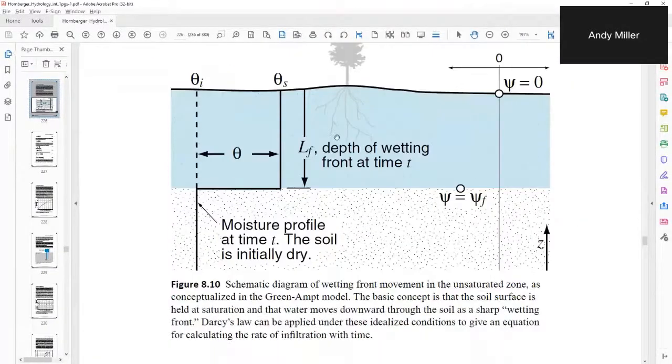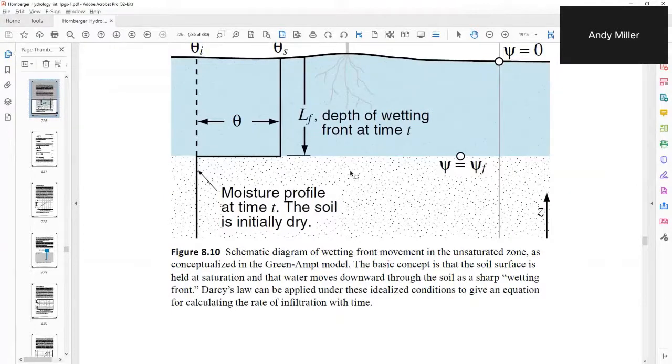So this is just a reminder that when you look at the spreadsheet, some of the things in it are really just a version of Darcy's law. If you want to calculate, using Darcy's law, the rate of downward transport, the infiltration rate, we're going to assume the infiltration rate, if this area is saturated, is going to be the same as the specific discharge in the downward direction that we got from Darcy's law, right?